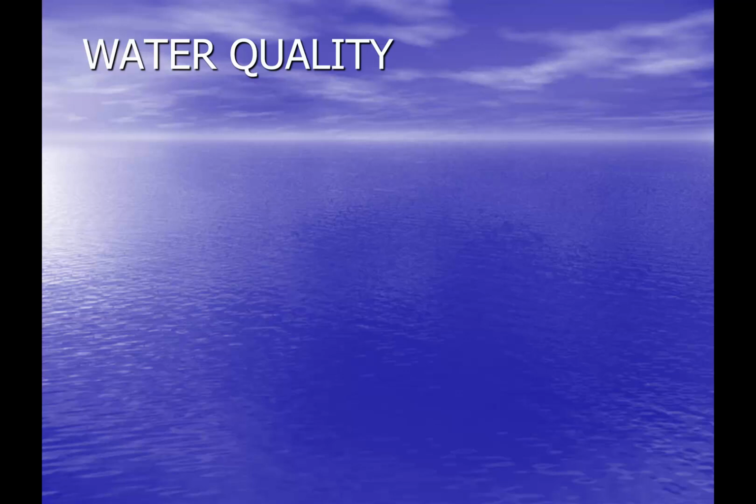While storage facilities are prone to increasing water age, and you can have declining chlorine residuals, you can have nitrite problems as a result. So it's important that we operate the reservoirs in a manner that accommodates or at least mitigates some of those water quality issues.